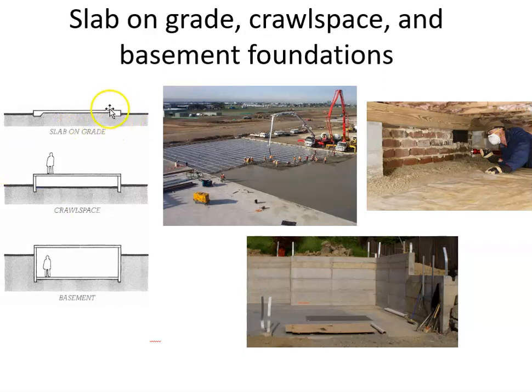Okay, and then how they take place. So again, down in the southern parts of America here, we could just do a simple slab on grade, reaching down 6 inches. Here's a crawl space, so that is coming down, whatever it is, 2 feet or so perhaps, and then it provides access to the underside of the structure. So maybe putting heating and air conditioning, for instance, down there could be a good thing. Plumbing could be down there. And then a full basement. So slab, crawl space, and what is going to be a partial basement at least.